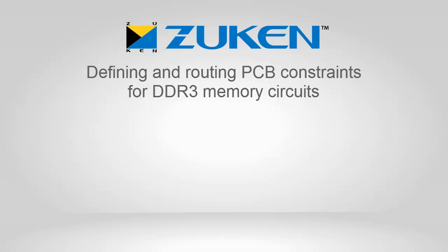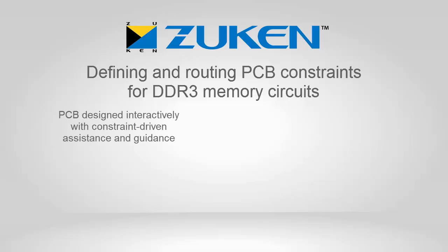In conclusion to the layout overview, I was able to constrain and route the DDR3 system within the layout application. From the results achieved, the application has provided a mechanism to ensure that the topology, skew, length and impedance balance routing requirements of the DDR3 system were achieved.